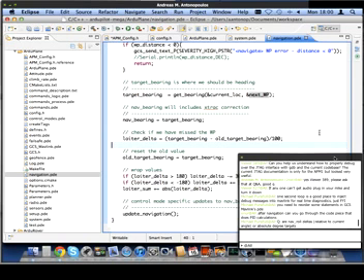So update navigation, the main output is what roll we want to achieve, and then it's up to the stabilization controller during the main loop, the 50 Hertz stabilization controller, to get the plane to have that particular amount of roll and the correct amount of pitch. So really this navigation is fairly simple.